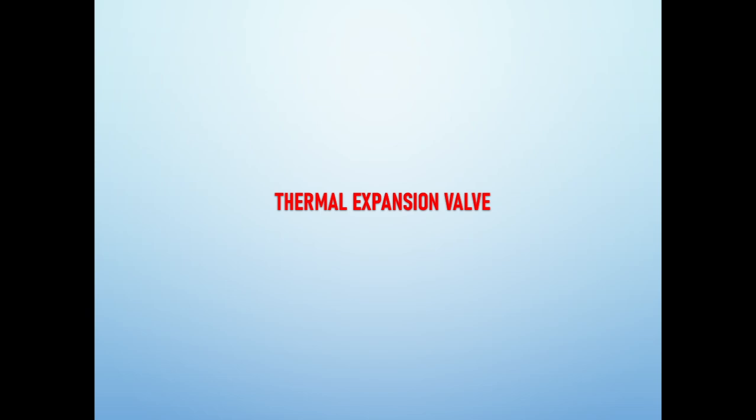Number one, compressor. It increases the refrigerant pressure and temperature. Number two, condenser. Releases heat, converting refrigerant vapor to a high pressure liquid. Number three, expansion device. Reduces refrigerant pressure and temperature. Number four, evaporator. It absorbs heat, turning the refrigerant into a low pressure vapor.